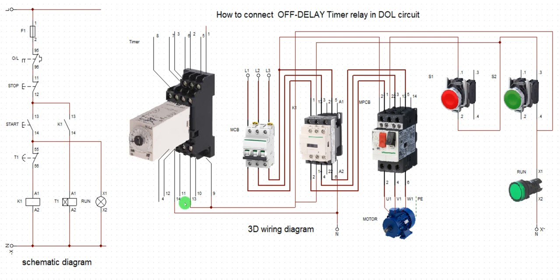Okay, all right. The same thing here is what is here. Then here is taken from direct starting button to my coil to my relay contact before feeding the coil. The same way, I want to feed this coil through terminal 1, like the contact I told you about that is coming from 9 and 1. 9 and 1 are normally closed, and I want to use that normally closed. Okay, so let's do that now. I feed my power from latching circuit to 9. I loop it to 13 to feed the coil. So this 9 is close to terminal 1. So when the relay is open, it will now break between 1 and 9.